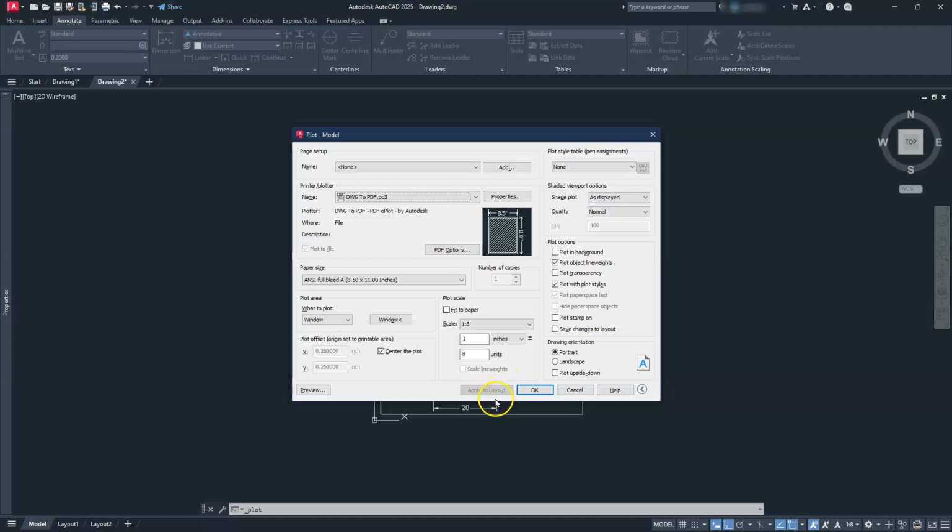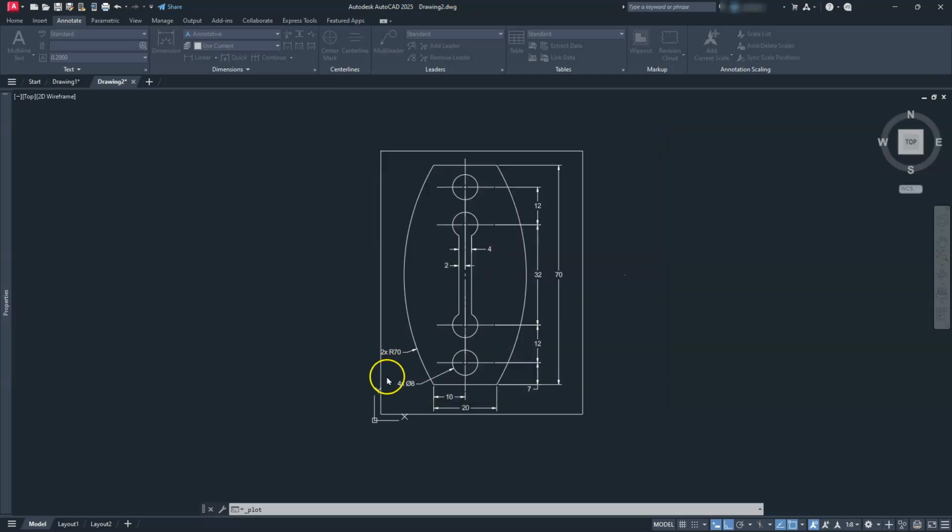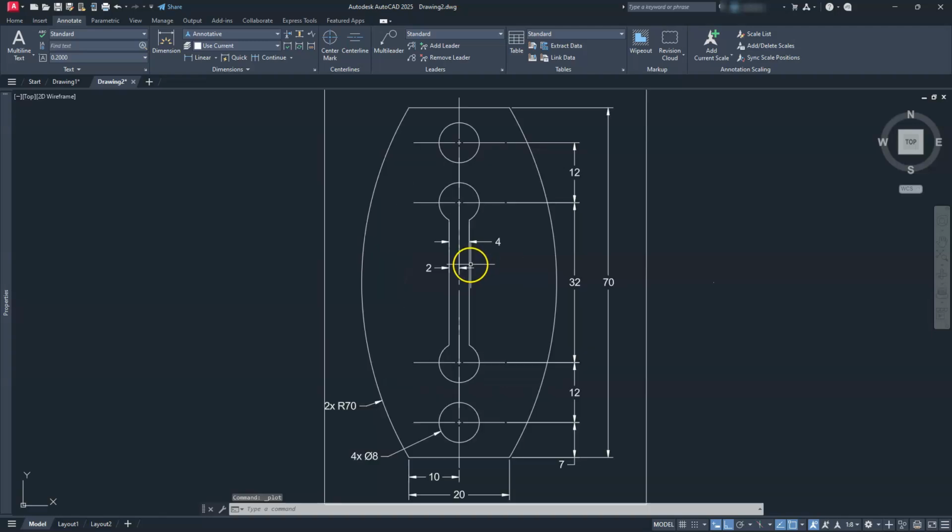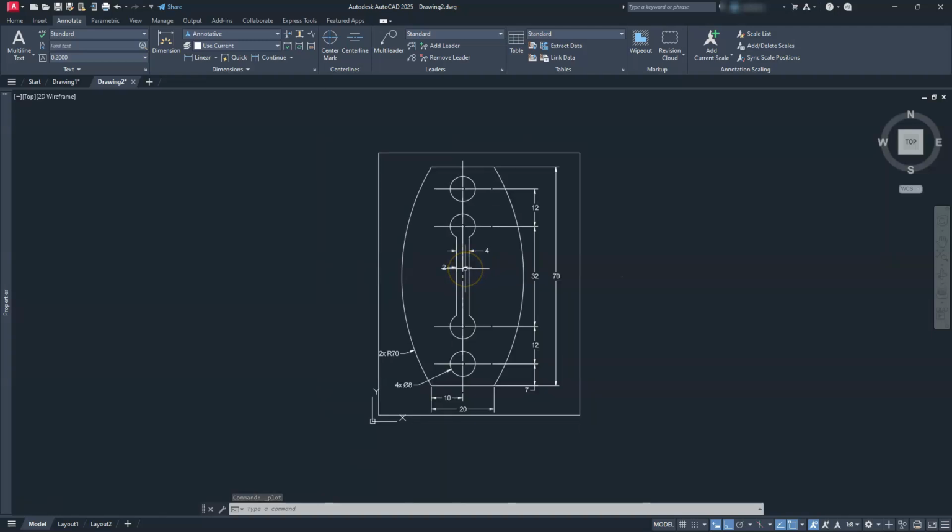All right. Another thing that you can do here is that if you wanted to make this monochrome or something of that nature, and typically when we print things, we typically print the black and white. So you can either use the grayscale or the monochrome. But that should be everything that you need to know, especially when it comes with printing this. Just make sure that anytime you see these dots out here, and I go to zoom the extents, this is part of the extents. AutoCAD sees this as a physical point or an object that is associated with this drawing.